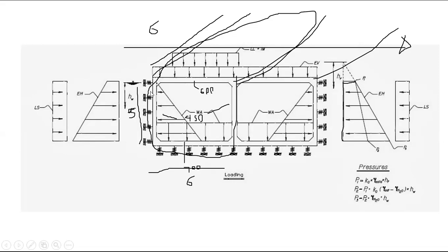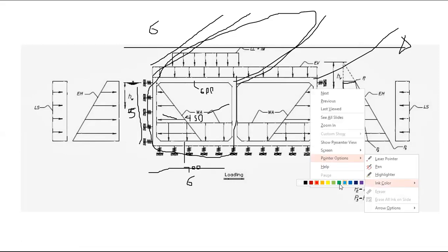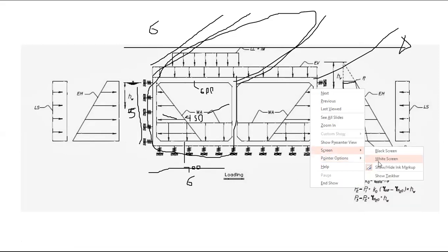And you will have spring supports for this one, because unlike if you model it as a pin support, a pin doesn't allow you to settle or translate. So it's not actually the realistic behavior, because the soil settles when the load is applied. So F equals Kx. If your x is a considerable value, then that means you have considerable stiffness as well, right? But if your x is 0, the only possible way is you have an infinite stiffness.